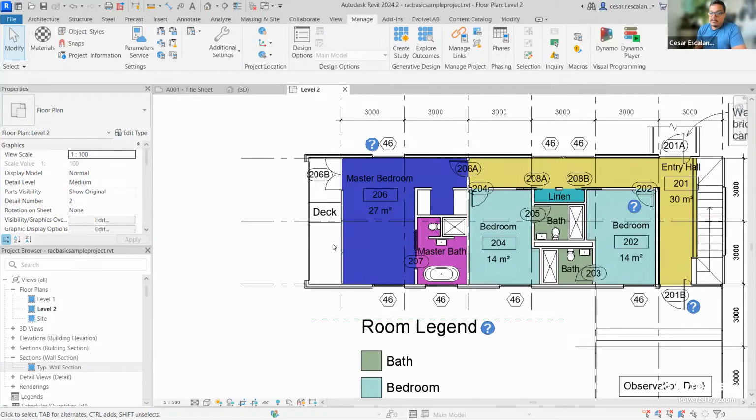And then the opposite happens with your counterparts. Think about the electrical drawings. Electrical drawings tone down everything about architecture, and then only the elements that are part of the electrical domain are really bright. And so there is this need to tweak the line weight value according to the purpose of the view.